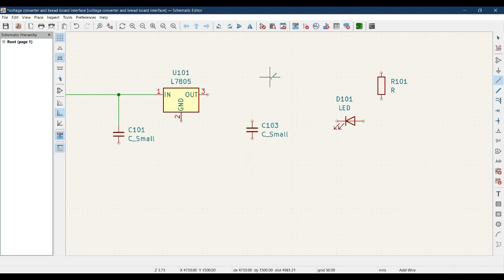As you see, there is a wire shape with my cursor, which means that my add wire tool is still selected. If I press escape, I will deselect my tool. Again I want to connect wire. The other thing is, simply hover onto this circle and its shape changes to wire. Now I click on it and I have selected wire tool and started to draw wire. I am going to connect with this capacitor. So a wire is connected between the capacitor C103 and pin number 3.